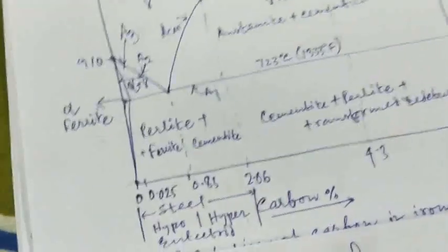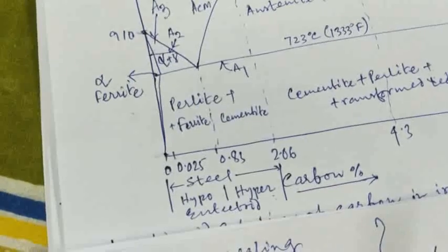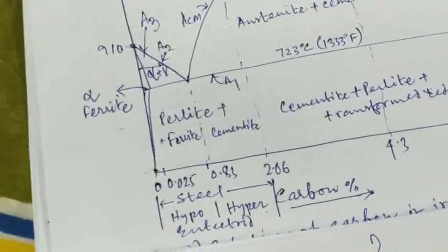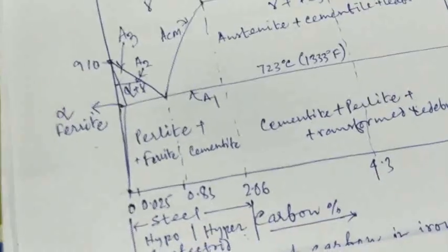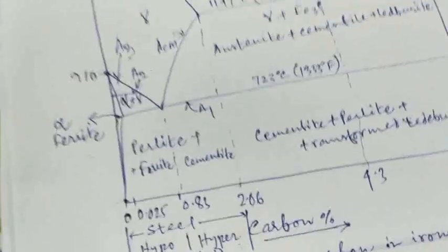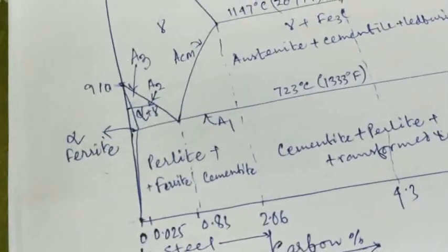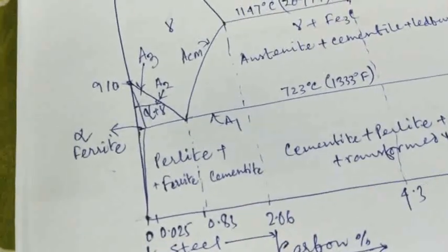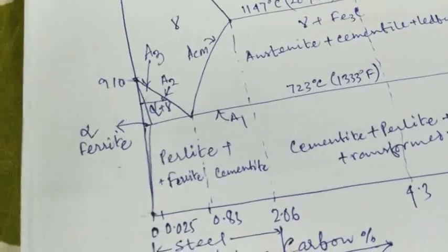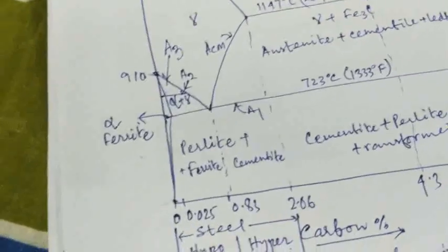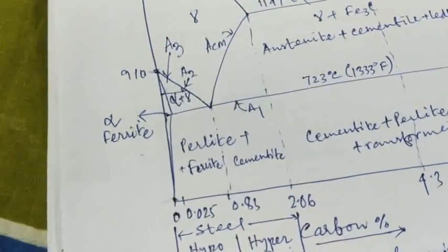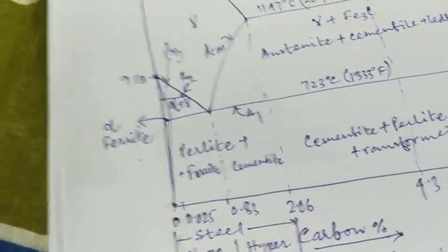The lowest recrystallization temperature of general material is 0.4, that means 40% of the melting temperature of the steel. The recrystallization annealing temperature should be 100 to 200 degrees centigrade higher than the lowest recrystallization temperature. The minimum steel recrystallization temperature is about 450 degrees centigrade. Slow cooling after proper heat preservation is required.